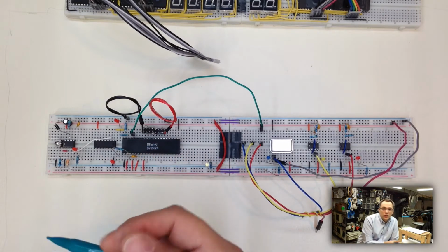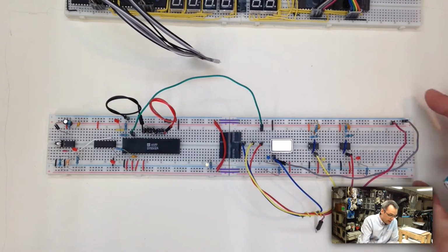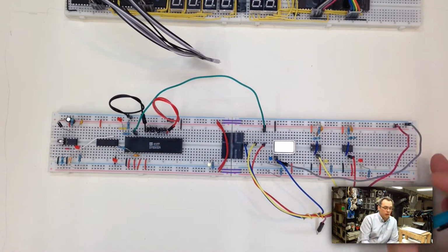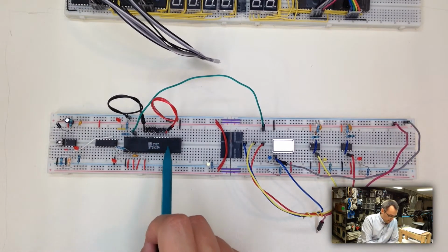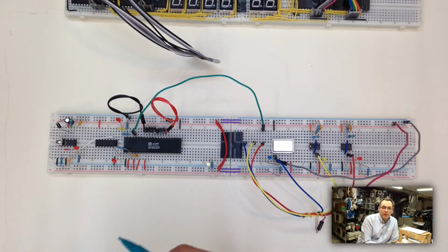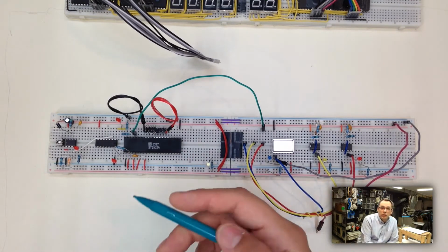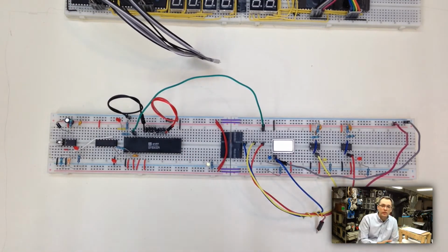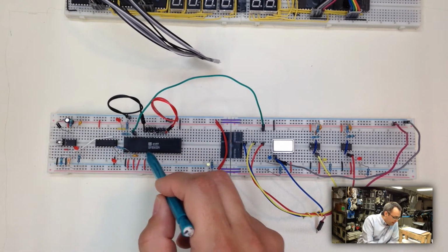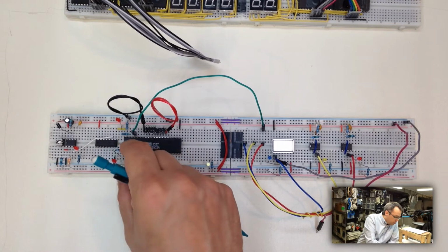That's a trick, or a problem I ran into, something I learned while working with these circuits: input circuits on chips do not like to be floating. They have to have either positive or negative. They have to have some signal on them. If you leave them floating, they do weird things. They don't work right. So you've got to make sure you couple pins that require inputs or outputs to what they need to be.